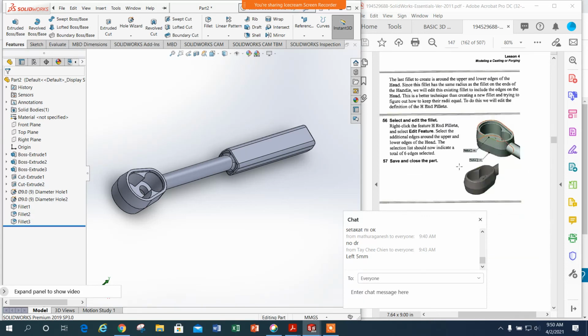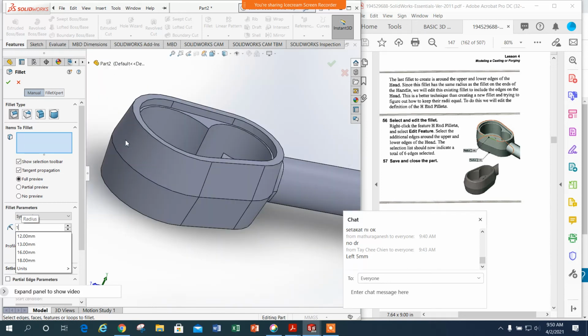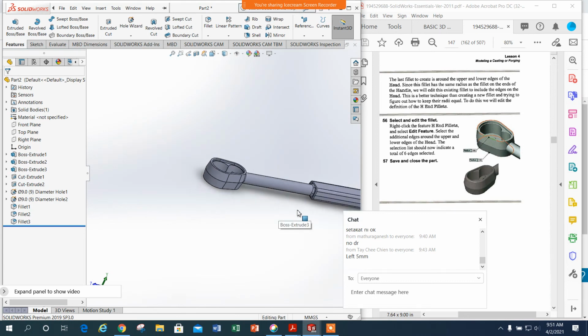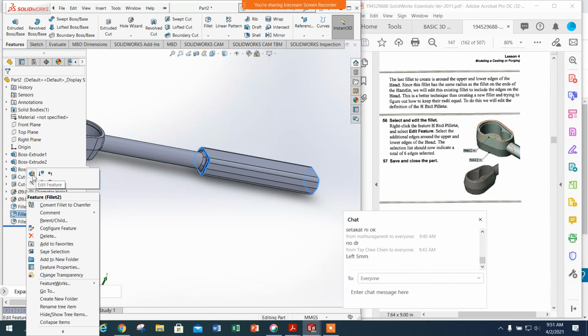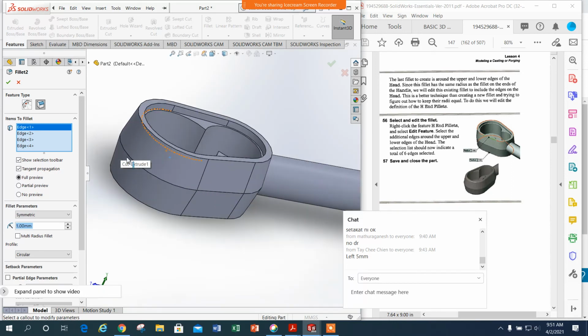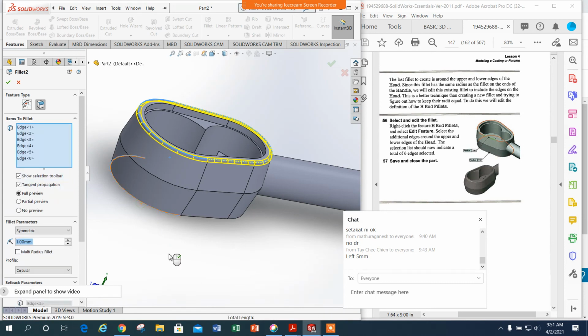And then last but not least is this one, 1mm. Oh, you can use this, in the example here, since the 1mm fillet is here, the 2 ends, the end here is 1mm, you can just right click, edit the features, and then you can add another edge that you are going to apply that 1mm fillet. This one 2. Click OK. Done.